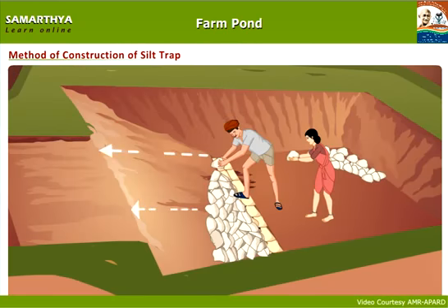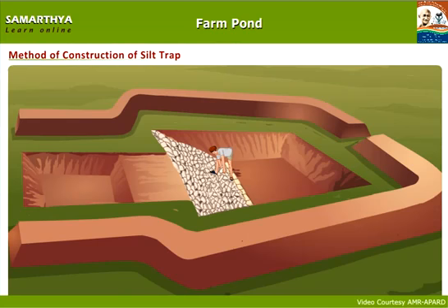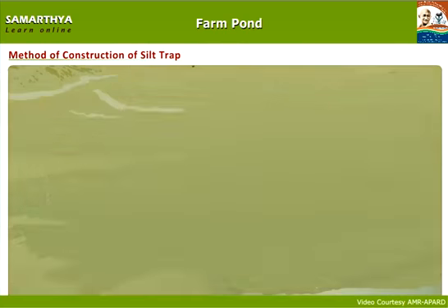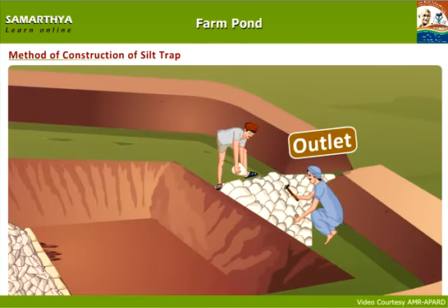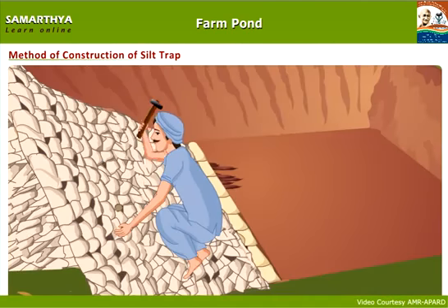A revetment using raw stones has to be made for the inlet wall in the path of the silt trap to the pound, that is 2 meters, and at the base of the inlet side of the silt trap and at the side wall of the pound. Some revetment also has to be made at the outlet of the pound. The gaps in the raw stones have to be filled with small stones and hammered properly.